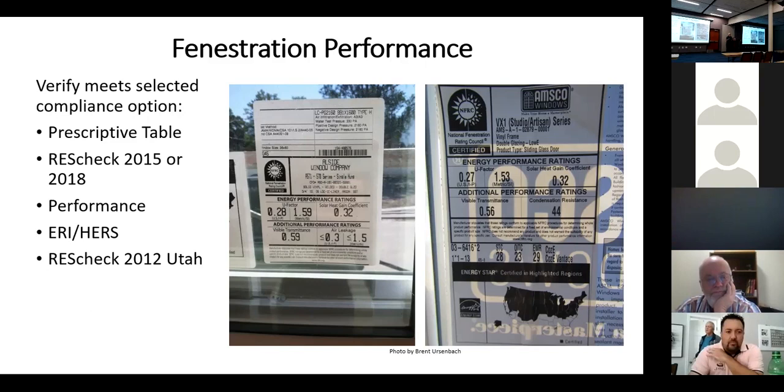So just to help bring this back into perspective, and so everybody understands, we talked a little bit and there were some people that understood it. In fact, gentleman right here, when I said a 0.05 window, he did the quick math. That's an R20 window. We convert from U to R by simply taking the reciprocal, or we divide. To get the U, we divide the R into 1. So 1 over R equals U. 1 over U equals R.